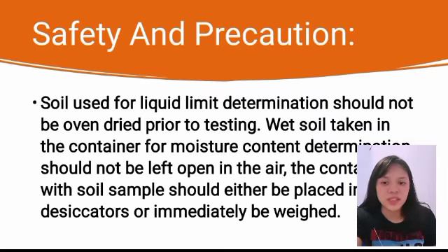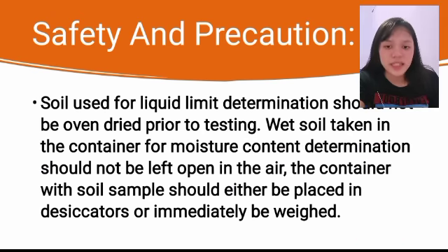Safety and precaution. Soil used for liquid limit determination should not be over-dried prior to testing. Wet soil taken in the container for moisture content determination should not be left open in the air. The container with the soil sample should either be placed in a desiccator or immediately be weighed.